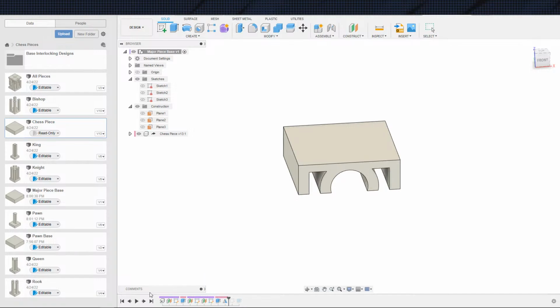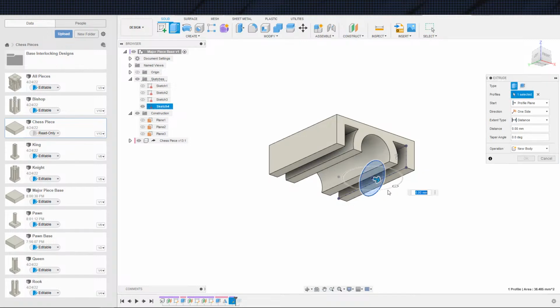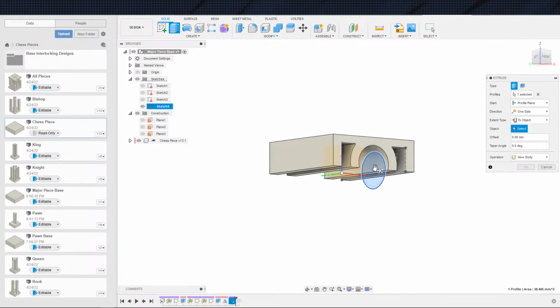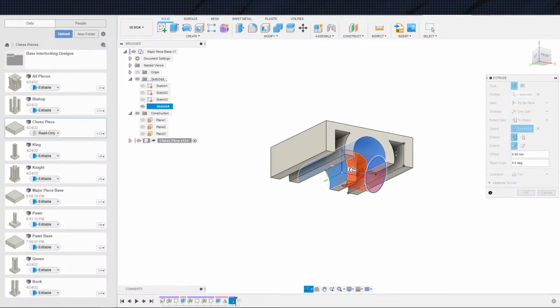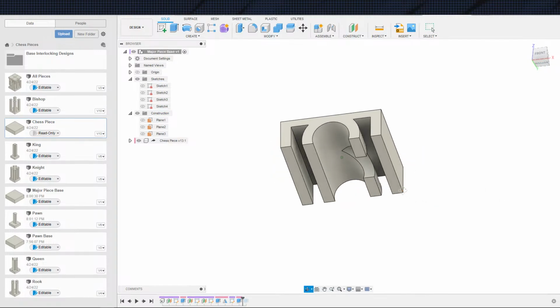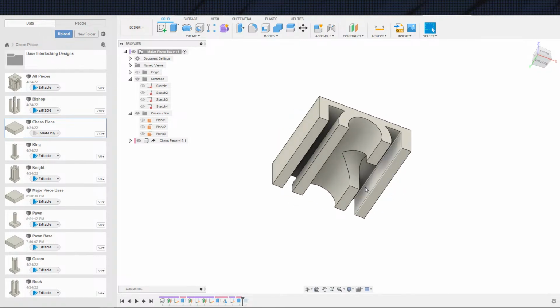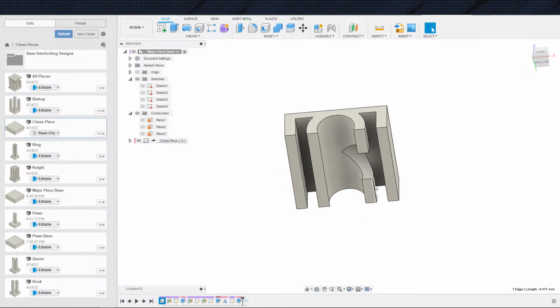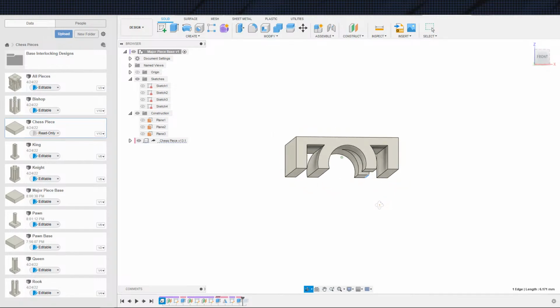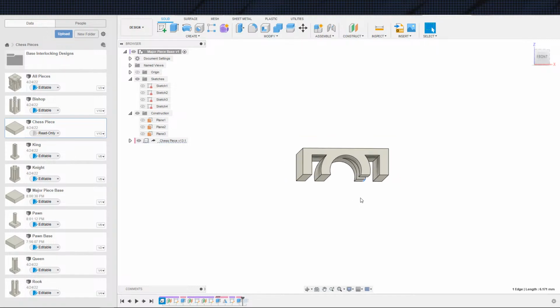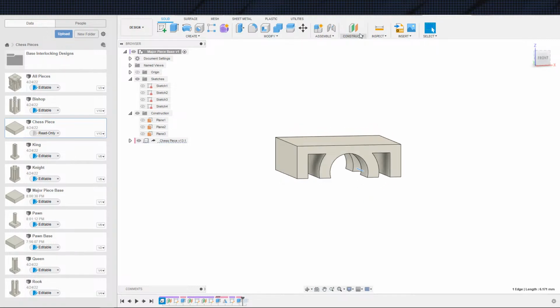And now, this next sketch that I made, I want to extrude this one, distance to object, and I'm just going to extrude it rather straight through. If this to the outside of the clip is 2mm and this is a 2mm clip, then really the head should stop sooner. Let's just take a look at it.